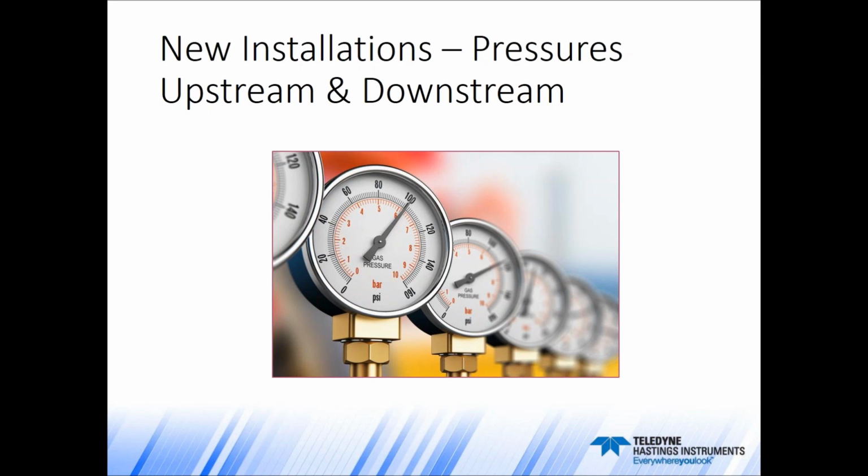Now, sometimes we find that in a new application, when a user's setting up for the first time, they may not have a full understanding of the pressure conditions, like what the pressure is right at the entrance to the flow controller. We're happy to work with them to give a wide range of pressure conditions for the valve. And often, if they just give us a simple napkin drawing of the system, that will allow us to help with the MFC selection. Now, a couple of other issues we see with new installations.